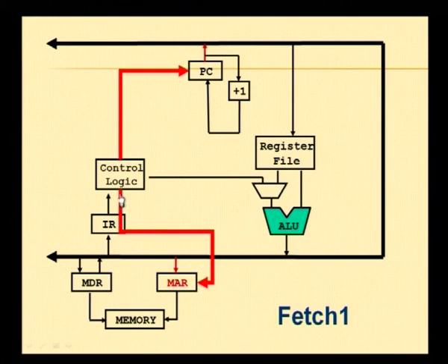So it is giving one more control signal here, telling the memory address register that whatever is there on the bus, you take it and store it here. So something is being put onto the bus and that is being stored onto this address register from the bus. Okay. So by means of these control signals, you are taking the value available in PC, which is the address, and storing that value in this address register. This is the first part of the fetch step.